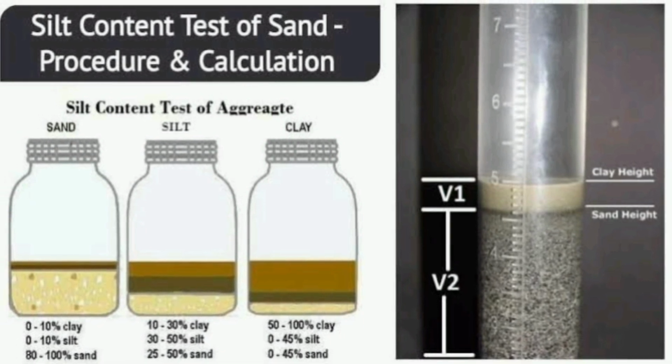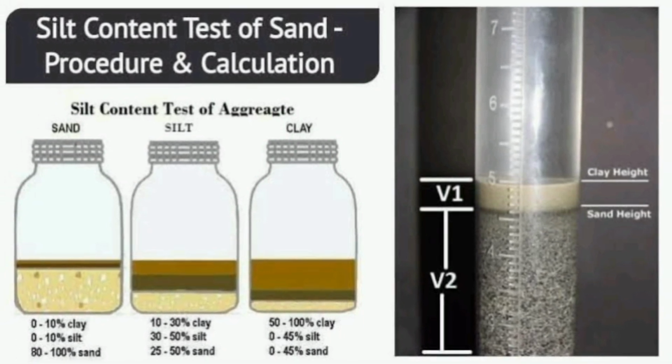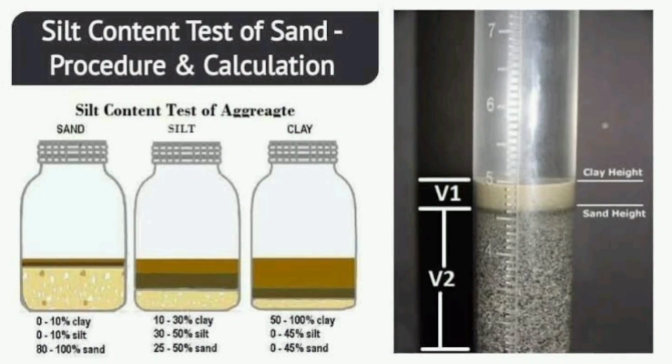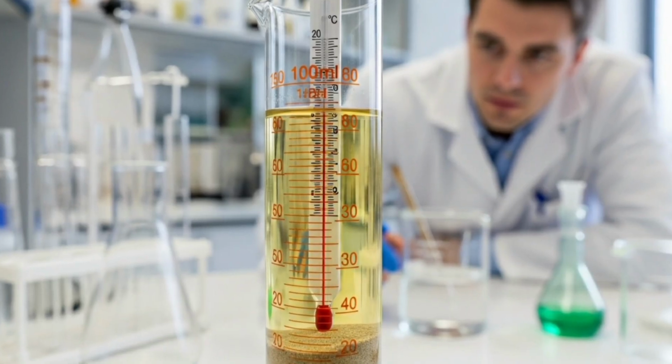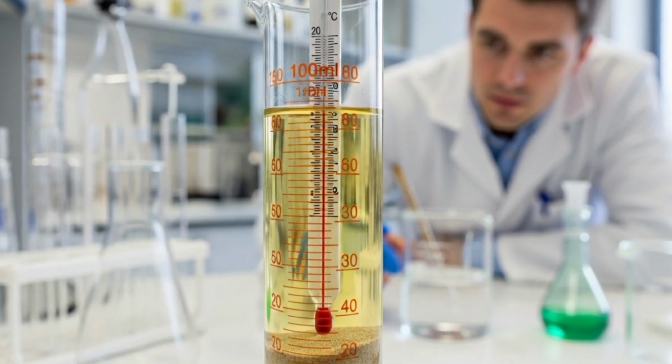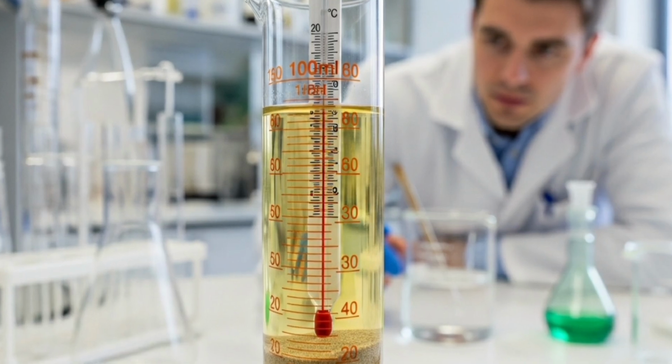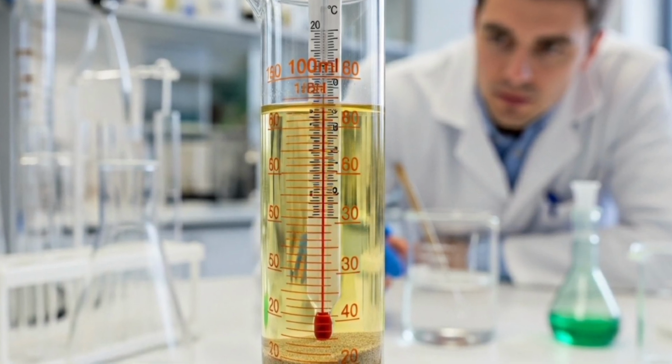For a quality mix, you want a consistently high specific gravity and a low water absorption value. A high absorption value means you must account for this water in your batching calculations to avoid a mix that is too dry and unworkable.